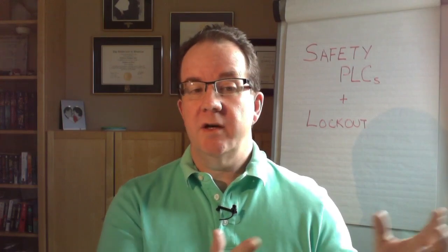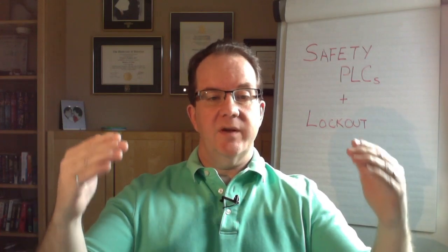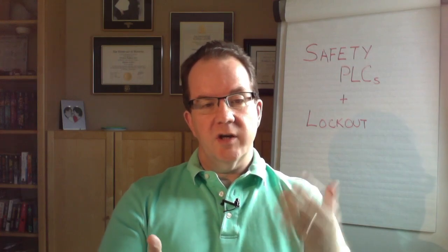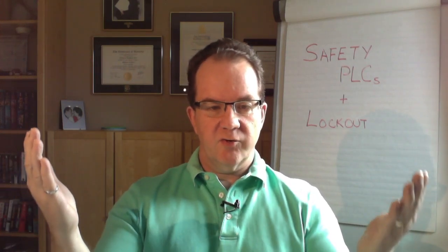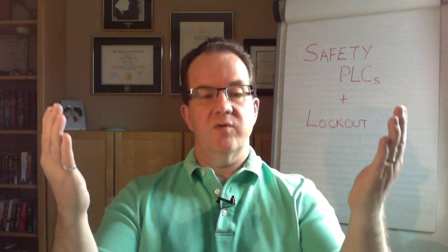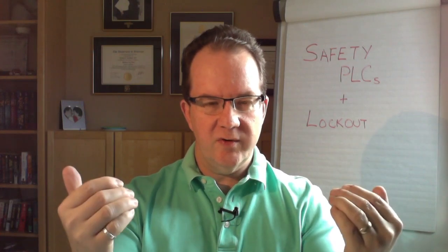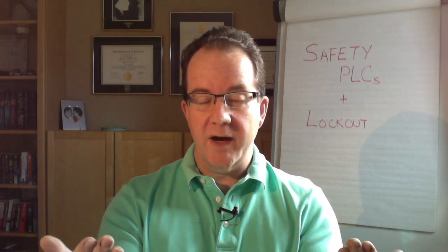All right. So my money would be on the disconnecting means, personally, for dangerous situations. But that kind of brings us back to the first step, and the first step is always do a risk assessment. And so if you're trying to determine, are we going to use lockout, or are we going to use hazardous energy control, or are we going to use some combination of those two things, thing one in this process is a detailed risk assessment, because if you don't do that, you don't know what's happening, you can't make rational decisions, you will screw it up, I guarantee you. If you don't do a detailed risk assessment, it's got to be done.